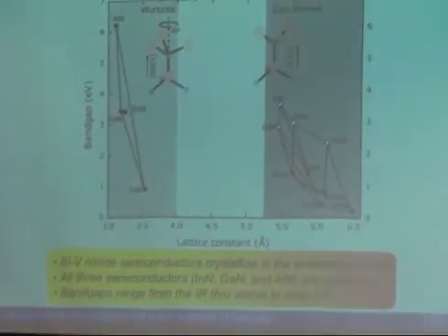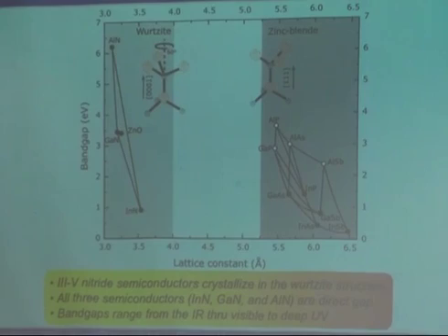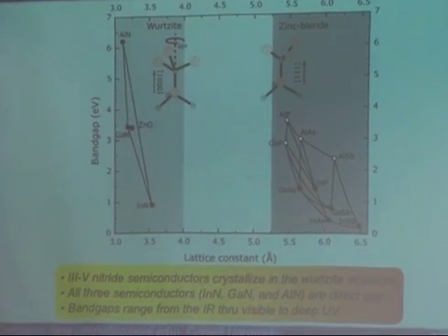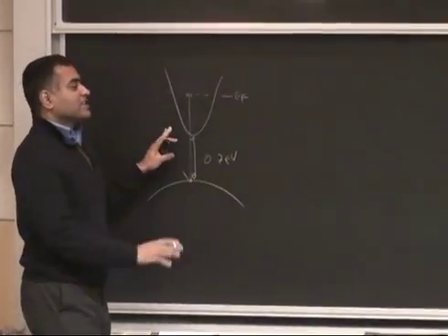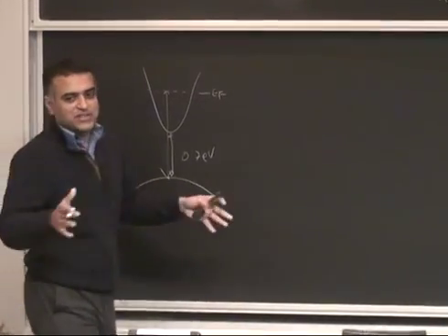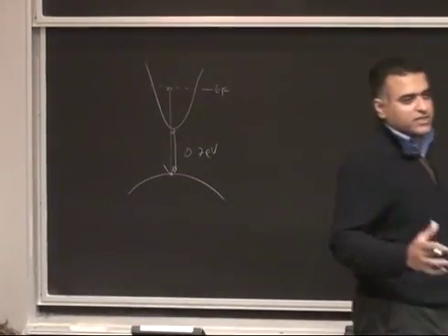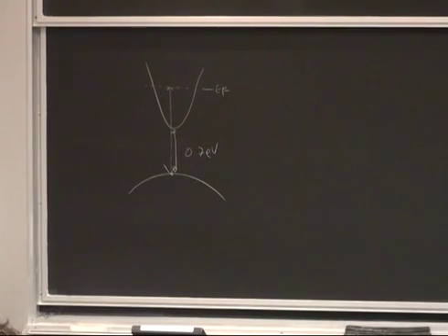most people believe today, and we have also done quite a bit of those measurements now, we think it's 0.7 eV. The better the material gets, the closer it gets to 0.7. In fact, it's getting closer to 0.6 now, but still very defective. It's a very difficult material to grow. All right, let's look at GaN though.